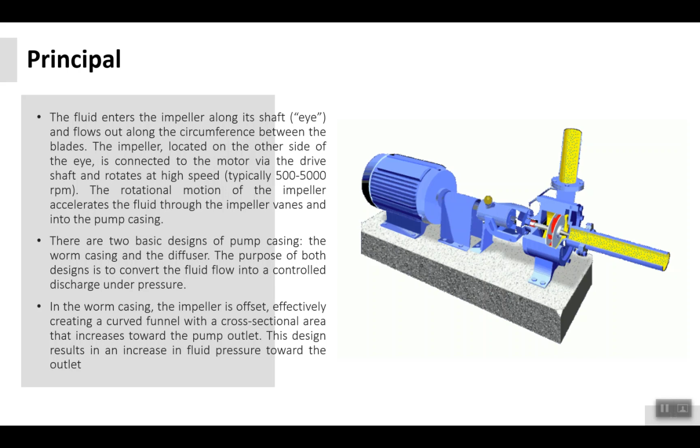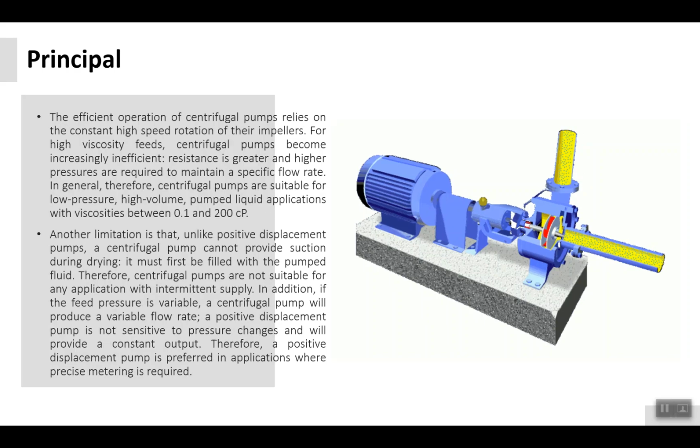In the centrifugal pump, as you can see in the picture, the flow comes in at the center and goes out diagonally from the impeller to supply the building. Typically the RPM is between 500 and 5000. It is typically used to supply hot and cold water to the HVAC systems in the building.